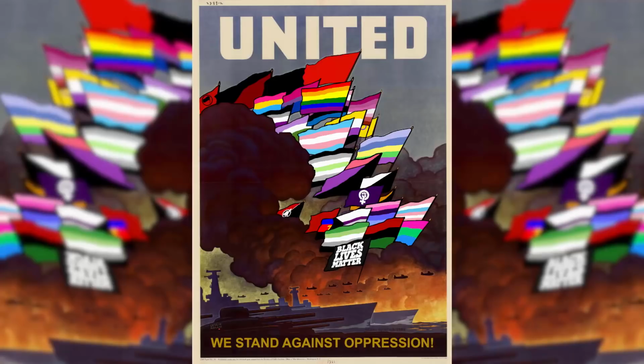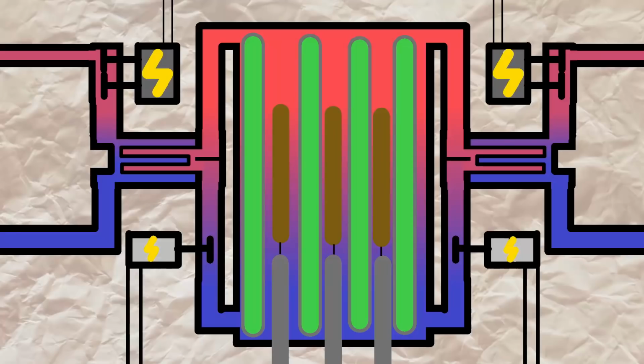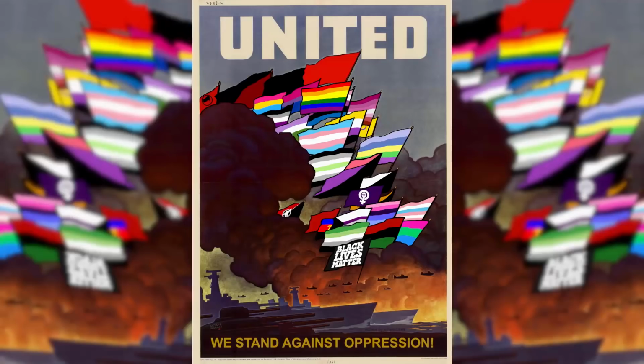The RBMK reactor was seen as very safe because it doesn't use high pressure vessels or enriched uranium. This means that even if there were no control rods in the reactor and no cooling water, it cannot explode. It would become really hot and it would melt and most likely melt through the floor and contaminate the groundwater, but it could not explode no matter what, in theory. So, what happened on this early Saturday morning?